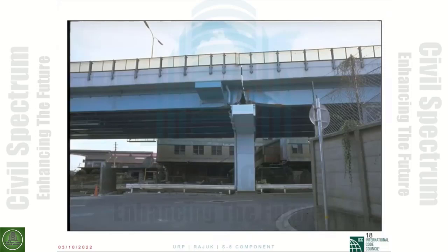Here you will see damage at the plate girder. This damage is caused by the forces in the cross frames. As you see at the location of the cross frames, this is a straight bridge, by the way. For a straight bridge, most of the time the cross frames are really secondary members for the gravity load. But for seismic load, the cross frames at the support locations become primary members, as we have in the AASHTO specifications.